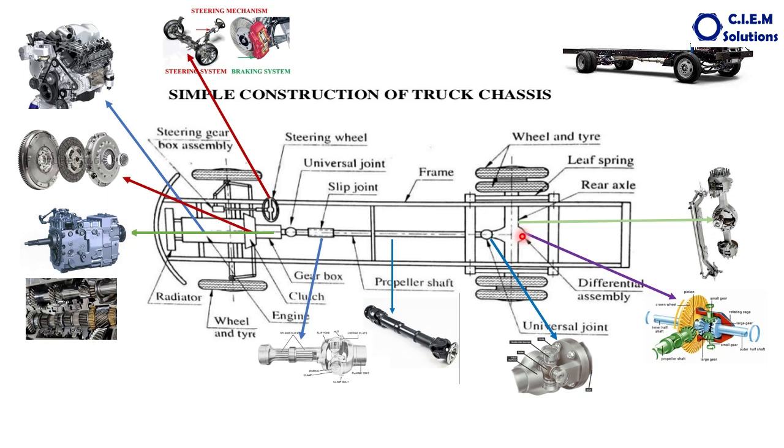To absorb those vibrations or shocks, a suspension mechanism is provided with each and every wheel. If there is no suspension mechanism, the vehicle chassis or the metallic link components fitted to the vehicle are going to crack or break. Not only for the vehicle, it is also not safe for the driver or the passengers traveling in the vehicle.